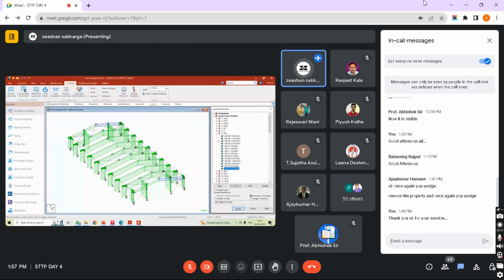Again, at the end, I have half the loads what I have generally. This is one wind load. Again, I have these kind of eight wind load cases. Four earthquake cases, eight wind cases, and dead load and live load. These are the various loads which I have. Then, based on these loads, we have these many combinations. And again, after that, we have this envelope.